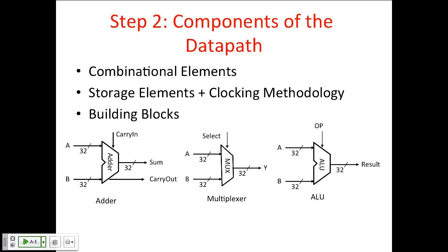So now we start building up a bag of components we're going to throw together. We're going to need combinational elements as well as sequential elements, storage elements. Remember, the combinational elements just respond to their inputs and at some time later produce their outputs. The sequential elements respond to the clock and only update their output when the clock edge arrives.